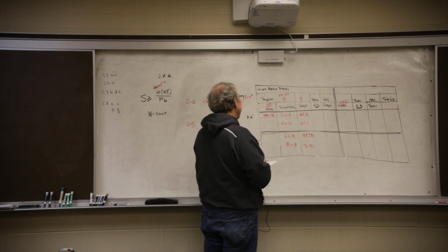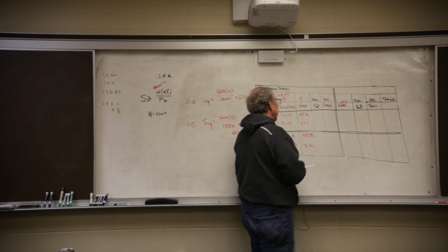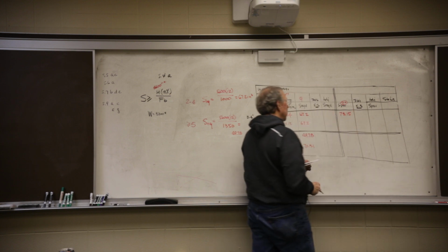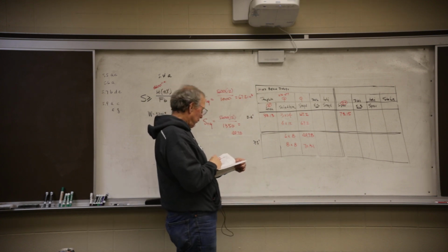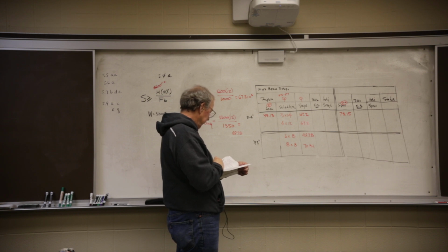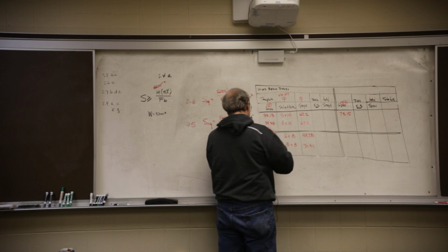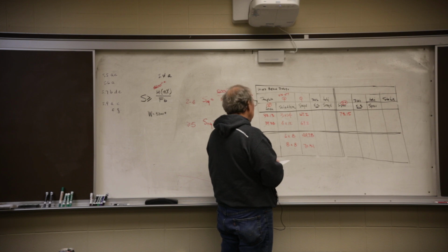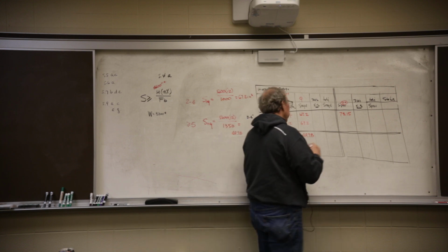We picked it by looking at a number, and the number we looked at was 7315. That's provided. So this is from the table. Provided and area come from the table. Move down to the 4 by 12. 4 by 12 has an area of 3938. And it has a section modulus of, 4 by 12. Where are you at, baby? You're right there. 7383.